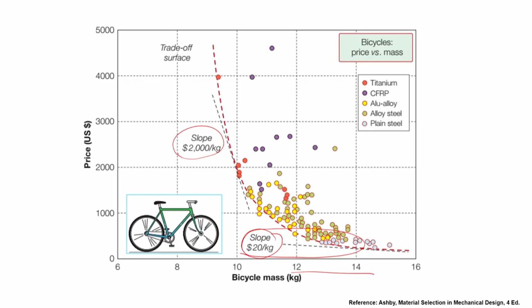So, you can see that titanium becomes an important choice here, whereas here you can see the plain steel becomes an important choice, because this side of the Pareto front is less mass sensitive, but this side is very highly mass sensitive. So, that is the way, by the use of value function, if you know the exchange constants, okay, you need a bit of experience to do it, you should be able to actually choose the material corresponding to compound objectives. And not just one objective, but there are multiple objectives. If there are more than two, let us say 3, 4, 5, then this curve will become multidimensional in nature. That is the way we can solve the problem.